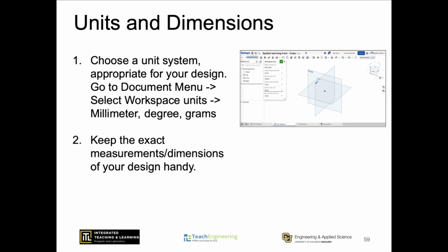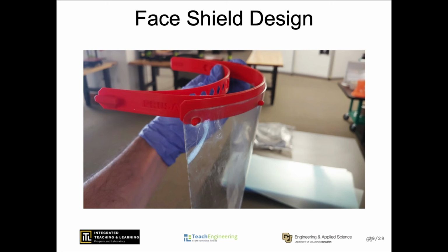The units and dimensions will be important. Choose a unit system appropriate for your design. Go to Document menu, select Workspace Units, and then millimeter, degree, or grams. Keep the exact measurements or dimensions of your design handy. For a better visual, this is what we are designing.